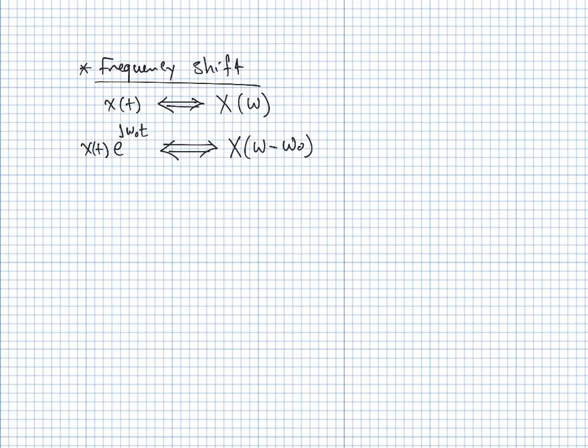So more or less, it's the same thing. The only difference is that shift in frequency does not produce a minus in the time linear phase shift, right? It just becomes omega naught t directly, okay? And the other one, it was t naught omega, but with a minus sign, okay? So that's the only difference between shifting in time and shifting in frequency.